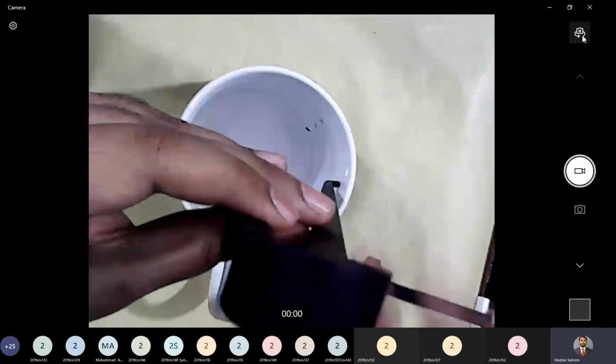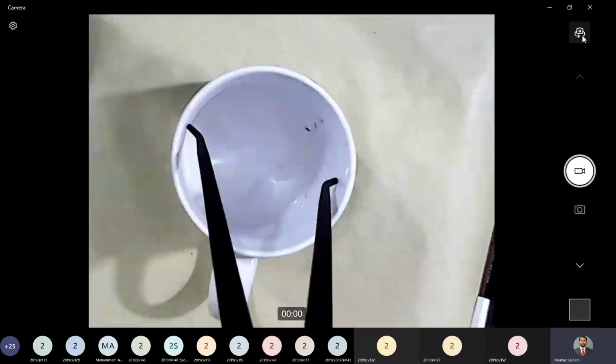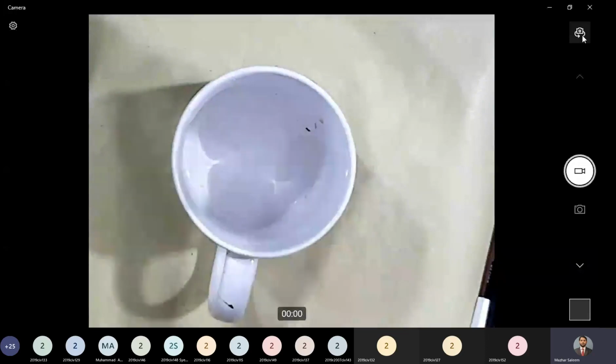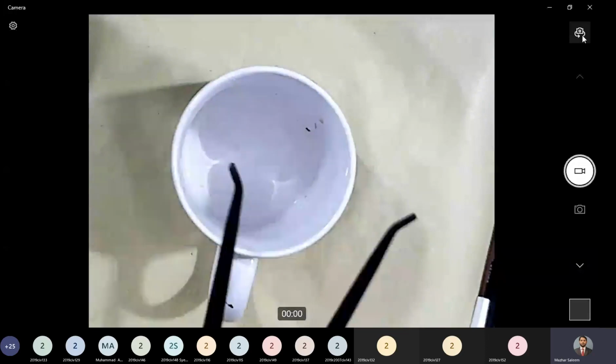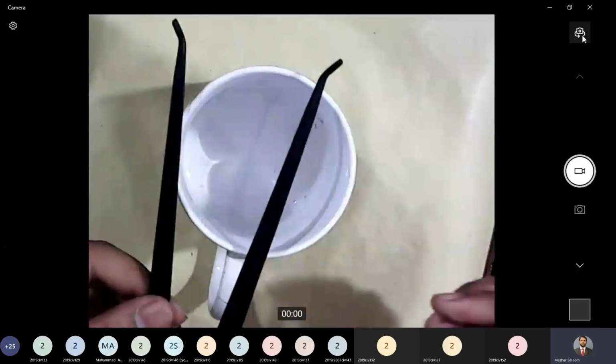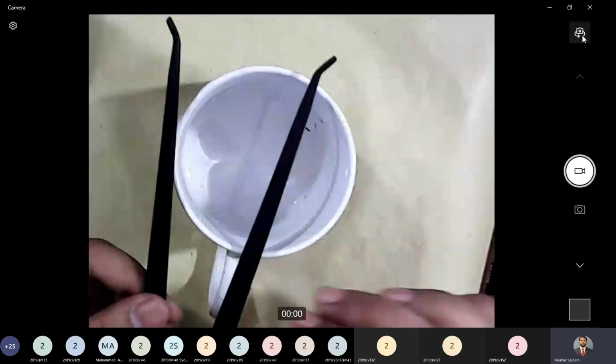And once it is opened exactly equal to this inside diameter, I'll take this device out and put it on some steel rule, and I'll read how much this dimension is. So that will help us in measuring the internal diameter of this cup. The spring divider and this instrument, the inside caliper, do not have any scale, so they don't have any least count or precision level. It all depends upon the steel rule that you are using later on to measure this opening, right?